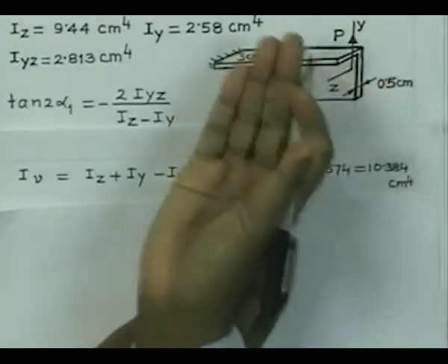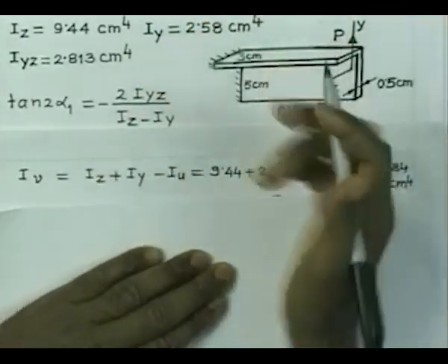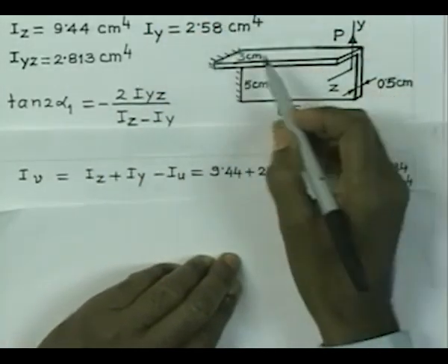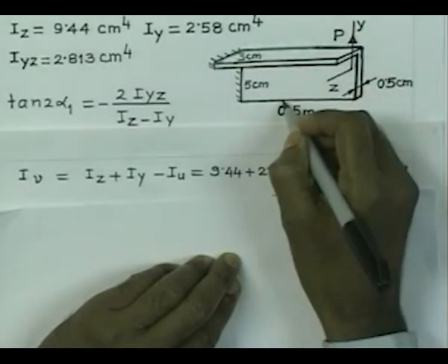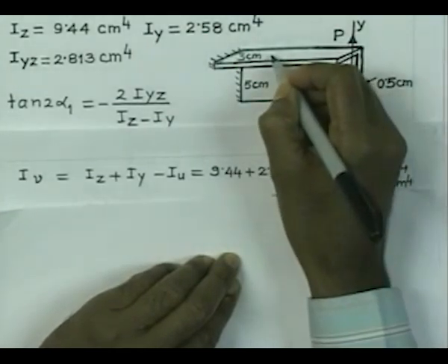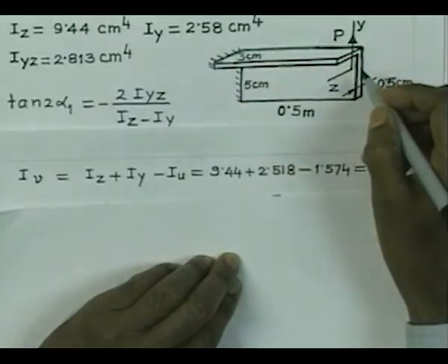So, it is trying to do like this, it will go bending like this, and there will be stresses acting there. Obviously, we expect tensile stresses to be occurring in this region and compressive stresses at the top fiber region. Now, we have to find out the extreme stresses.